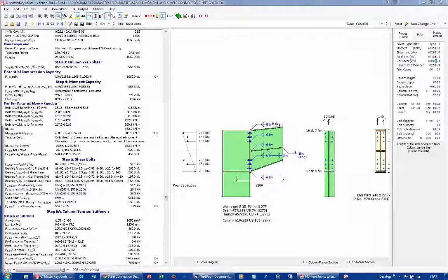There are one or two little weird calculations involved for alpha B's and stuff like that, and K ones for getting your bearing lengths and capacity. But in the end, it comes out pretty similar. The only problem you have is when you are relying on some of your tension bolts that weren't fully loaded to give you additional resistance.